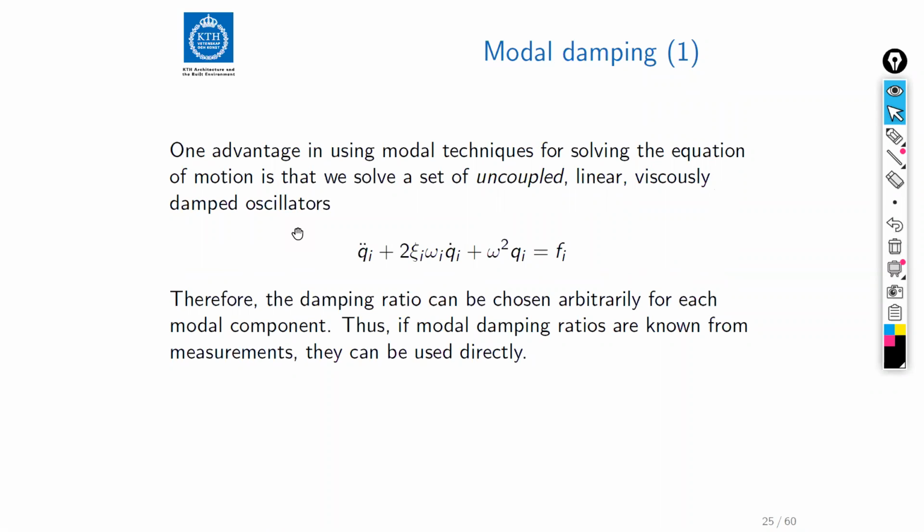The point here is that now we have moved on to the next topic here. So we have defined how to choose the Rayleigh damping parameters. And this, I think, is perhaps the most important way of modeling damping when you are working in the time domain. Because most commercial finite element codes give you only that option. In a linearized analysis in the time domain, you essentially have only Rayleigh damping to work with.